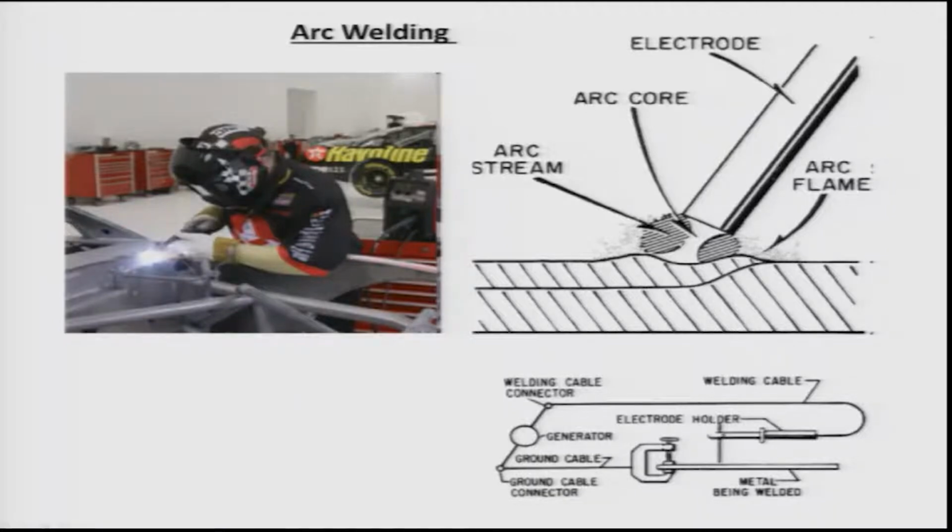Here you see there are two pieces of metal getting joined together using an arc flame. In this situation only a small amount of liquid is generated between the two pieces of metal, and because the liquid is in contact with the two pieces, there are an enormous number of heterogeneous nucleation sites present on both surfaces. So solidification starts with the heterogeneous nucleation of these grains.